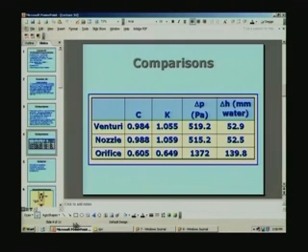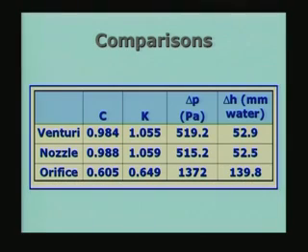So, with this we have finished looking at the variable area devices, and just to recapitulate, variable area devices are going to deliberately introduce a change in the area of cross section which will affect the velocity of the flow, and the kinetic energy is converted to potential energy in the form of pressure head, and what is measured is the pressure difference between two chosen stations or sections along the length of the installation.